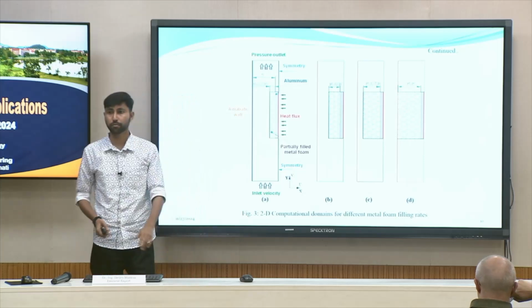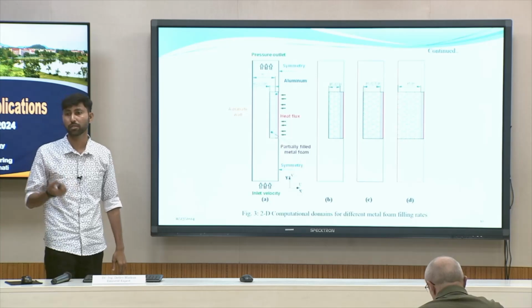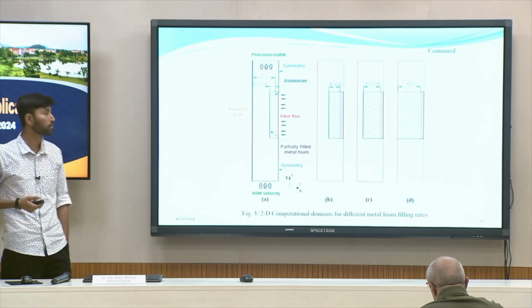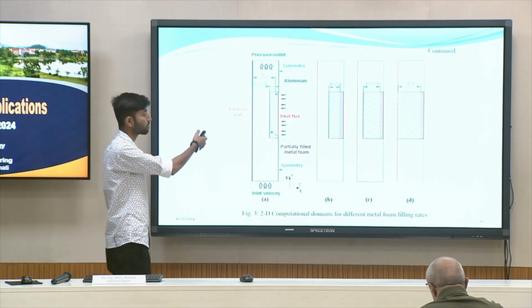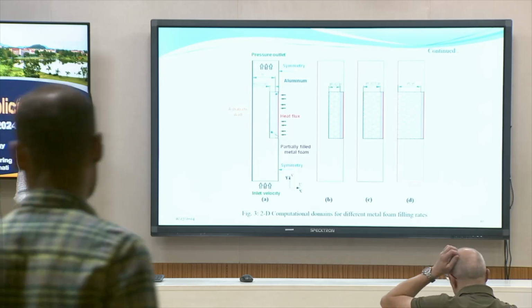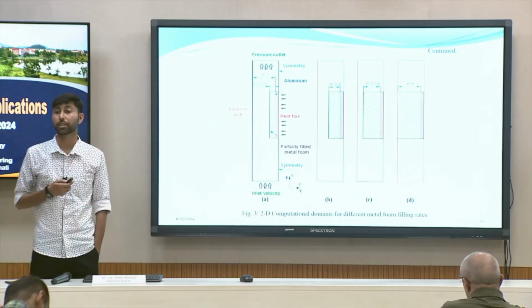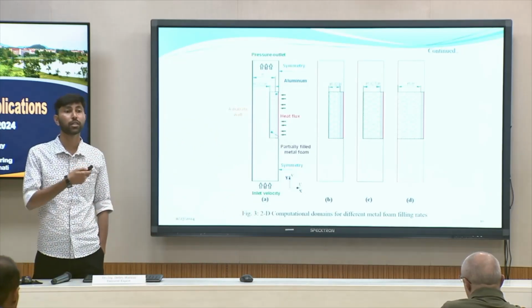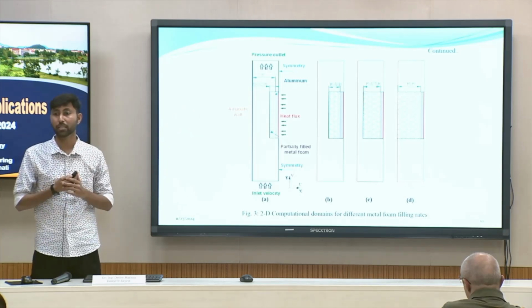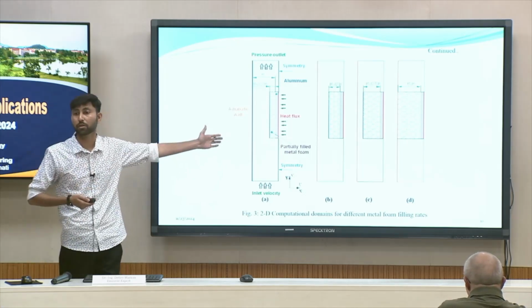as a symmetry. Here the simulation is performed by varying the velocities, like 0.1, 0.5, 1, so we have varied the velocities. For the different cases, the same boundary conditions were considered. It is observed that 100% filling gives more heat transfer. With completely filled channels, because of more surface area, more heat is transferred. But at the same time, the pressure drop is also higher in the case of 100% filling.